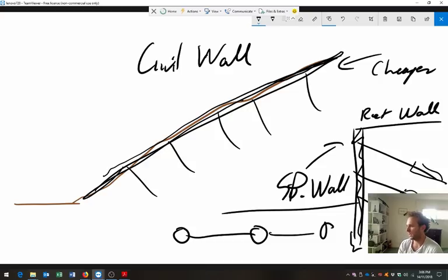Okay, so what's the maximum length of precast pile and beam used in Melbourne? Length. I think we can order a precast pile up to like 18 metres of length, but it'd probably be pretty rare we do it that long. Usually 12 metres would be our limit. But we can keep joining them together and hammering them in.